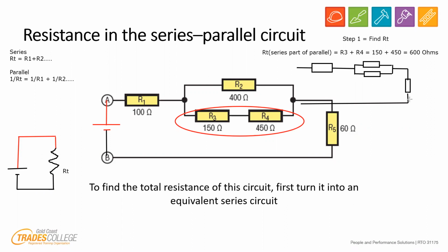So by doing this maths above, I have so far simplified the circuit that we started with to a circuit which has just a parallel circuit now in the way of the other two resistors that are in series. And we need to label it as well. Down here, we've got R1. We know what R1 is by looking at the first drawing, so I'll leave it as it is to make my life easier. We've got R5, which again is 60. We've worked out our new resistor.